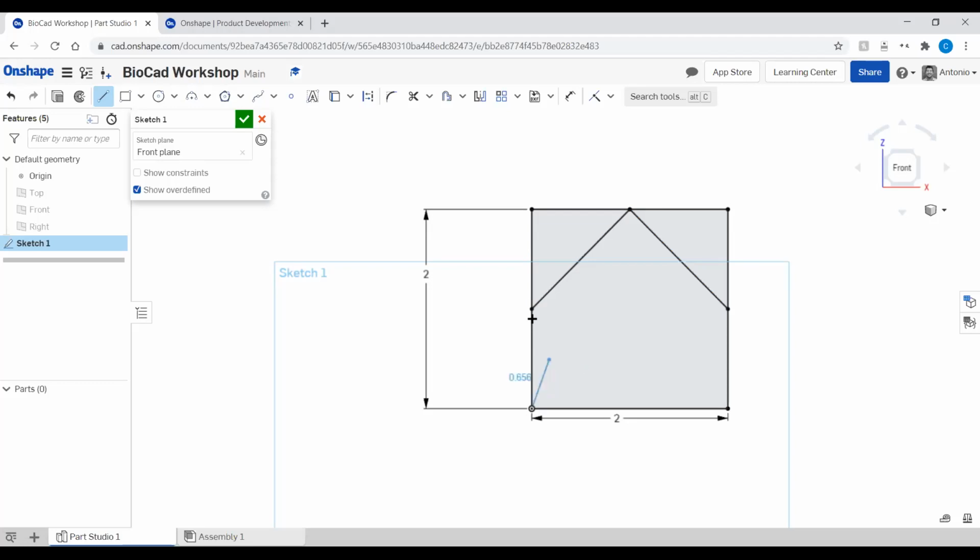Now, what you can also do is, if you find a point that you want, before you click it, slowly start to drag it to the right or to the left. You should see a couple of yellow dotted lines sort of guiding you towards the right. What that does is it fixes it using a relation to constrain that line. So in our case, we're constraining this to be exactly horizontal to that midpoint.